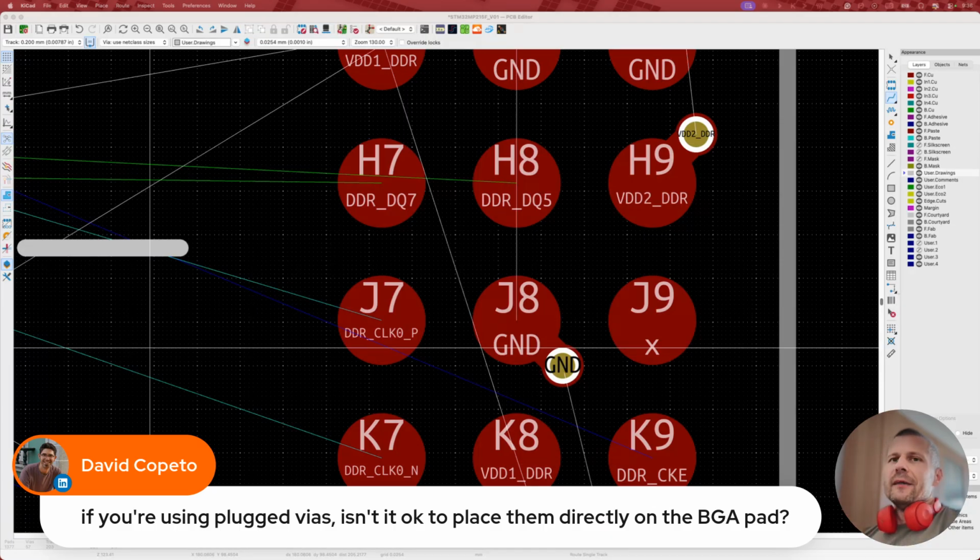I'm not an expert in PCB manufacturing, but if you imagine a pad with the via inside, the via is filled with some epoxy, but the pad is exposed and not covered with solder paste. So it's a question whether the epoxy filling of the via can protect the solder from sucking down, from wicking. I don't know how this unfriendly process of solder paste wicking or sucking down is called.